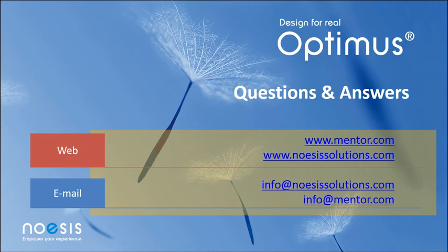There's another question here about the quality of the RSM surfaces. It says the most important fact of the response surface models is the quality. How do you make the decisions about the quality? So Optimus has a number of post-processing tools that allow you to gauge the quality of that response surface model. We give the user the R-squared values, the R2 press values, leave one out error, mean squared error, sum of the errors.